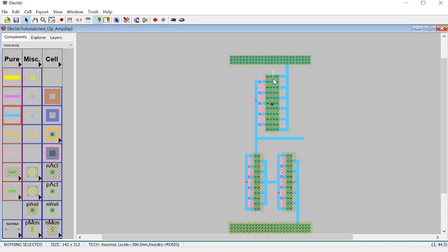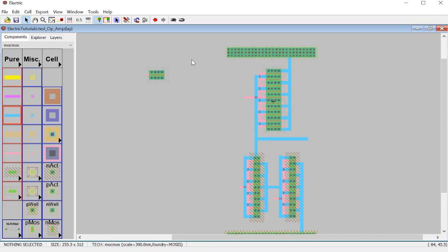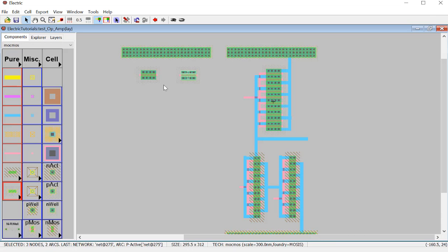If I just copy this one. So that's a standard PMOS, and delete the metals. So that's one PMOS, F5, no errors. So I need another top rail to be placed over here, and because it has 2 of them, I need to get another one, and they need to be in the same line.